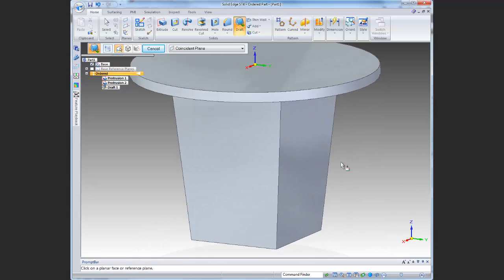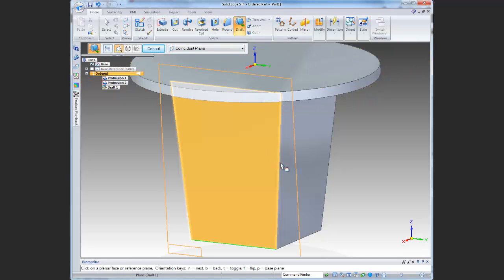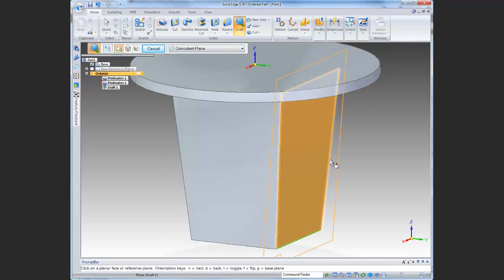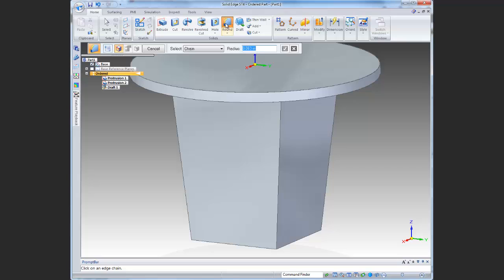Alright, so let's add some more things. Some more things that we're going to add are these edges here. You can imagine this would be down in a mold, so these edges have to be rounded because they're going to get cut with a tool that's going to have a radius. So really this is where you meet the real world and ask what size tool could actually get in there. To be honest, most tools we have in the shop won't go down a full 2 inches, but let's pretend like a 3/8 would work.